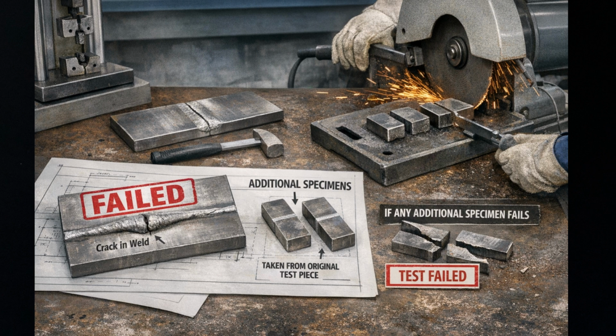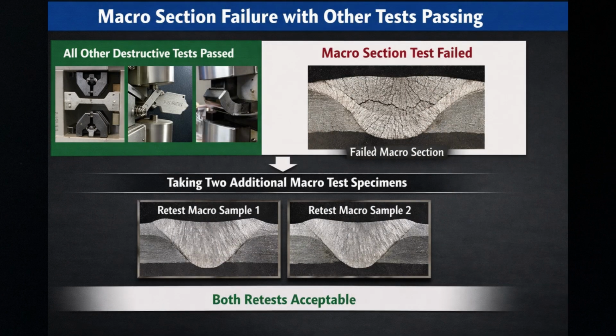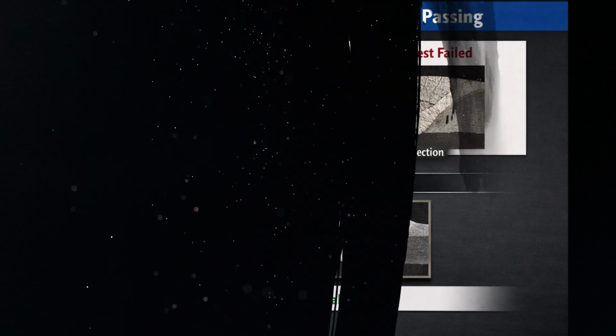If any of the additional specimens then fails, the welding procedure test is considered failed. Macro section failure with other tests passing. There is a specific provision for the case where all destructive tests provide acceptable results but the macro section test fails. In this situation, 2 additional macro test specimens may be taken from the original test piece. This is a practical accommodation. A macro failure is sometimes localized, and additional specimens from adjacent locations may show the true picture.